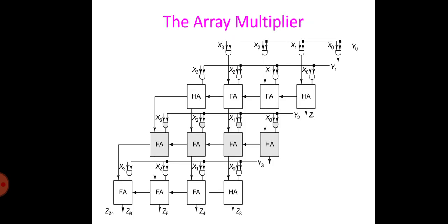So in simple terms, the modified Booth recoding essentially examines the multiplier for strings of ones from MSB to LSB and replaces them with a leading 1 and a minus 1 at the end of the string. For example, 0 1 1 is understood as the beginning of the string of ones and is therefore replaced by a leading 1, while 1 1 0 is seen as the end of the string and is replaced by a minus 1 at the least significant position.